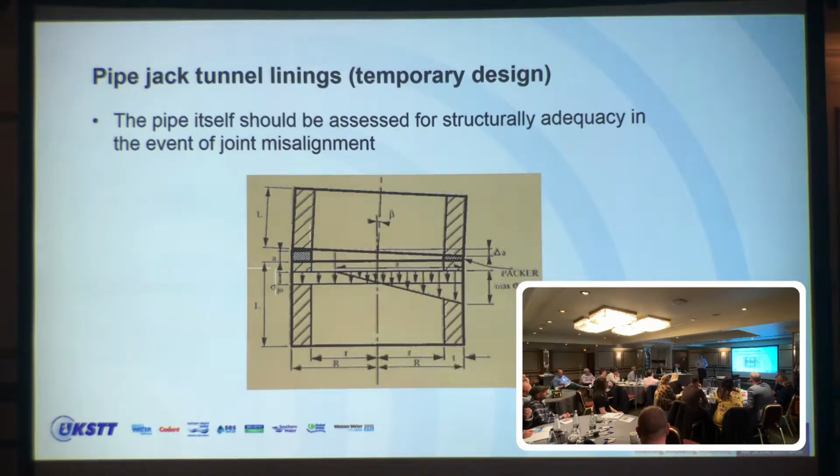Joints can always be at a slight angle, typically 0.25, 0.5 and up to 1 degree are generally what the loads provided for the capacity are. In terms of the pipe, you can see in that schematic that if this is one pipe and that's the next pipe, and you've got outer tolerance load on there, you may be getting more load or more stress on that side of the pipe. So it's a check that's worth doing.